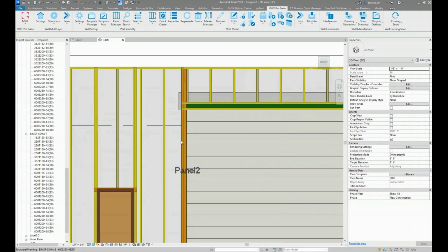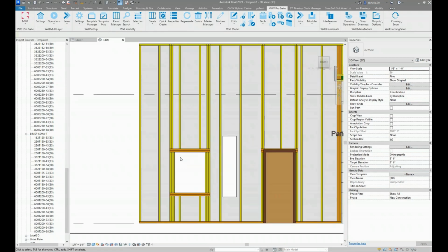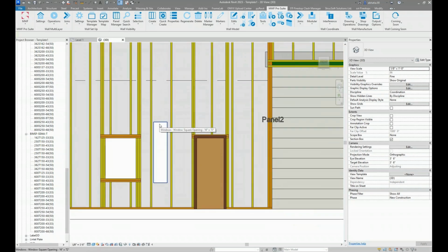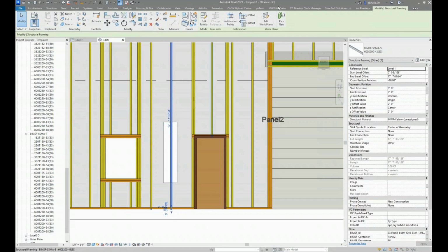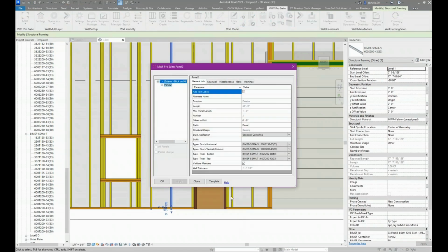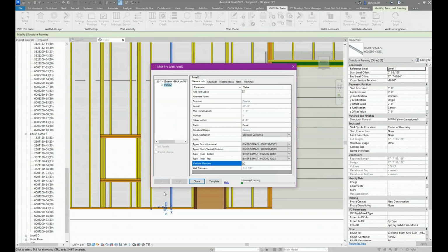But you can see here, it created the box header. This created the default openings, default non-bearing marker. It followed the rules for that. And this one is just ignored between studs. So if it's actually not in between studs, if I was to move this over, it would actually frame it. So let me just go into properties, template, this one, update, yes. Okay, set as active, close, okay. And you'll notice that it gets framed.